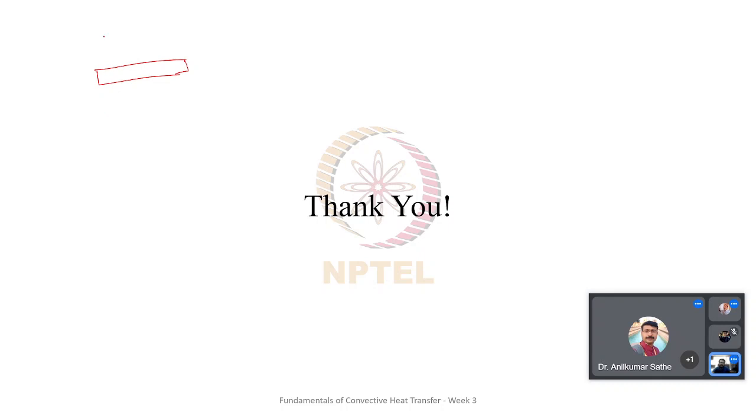It is at T infinity, and this entire metal rod is also at T infinity, and suddenly we start heating it with a candle, which is at a higher temperature, let's say T hot. What would actually happen in reality? In reality, the part closest to the location of heating would heat up first, and then there would be a gradual propagation of the temperature gradient downstream, and finally a uniform temperature gradient would set up.